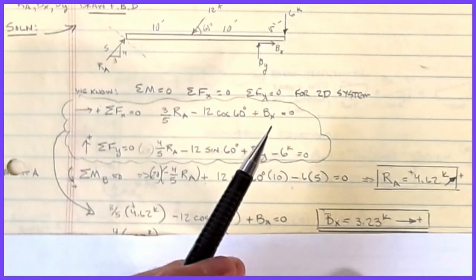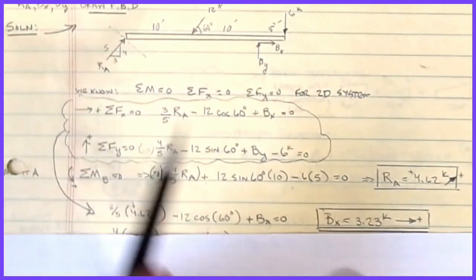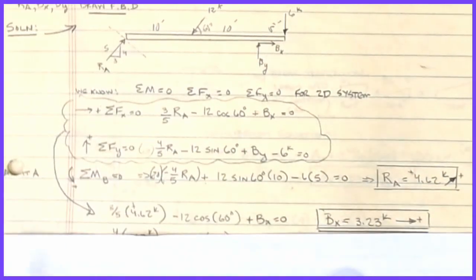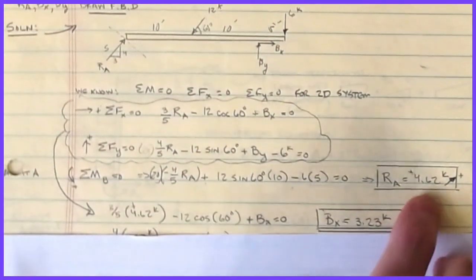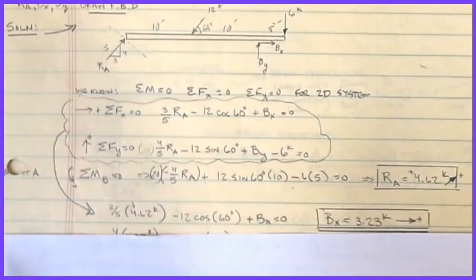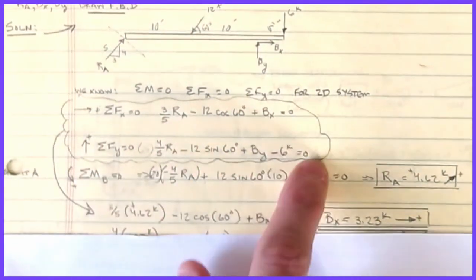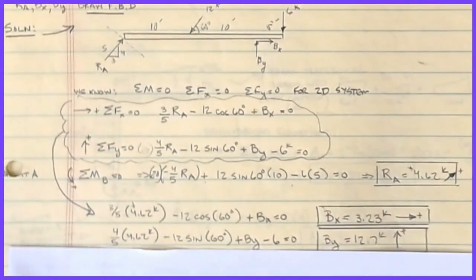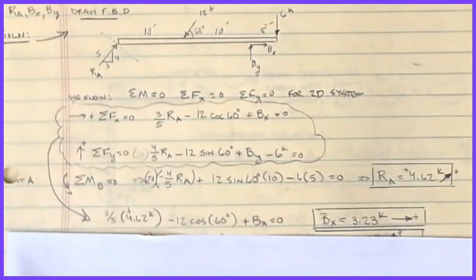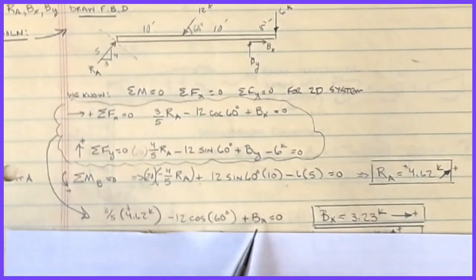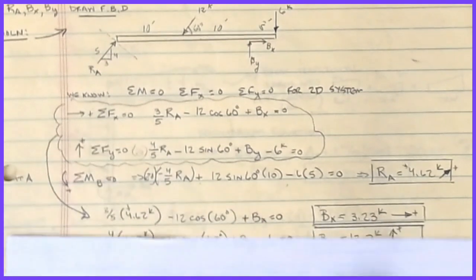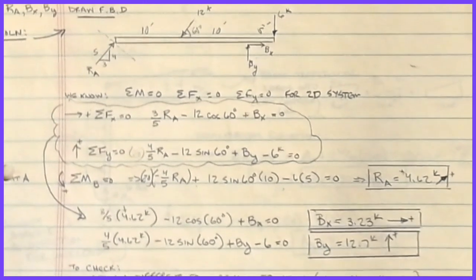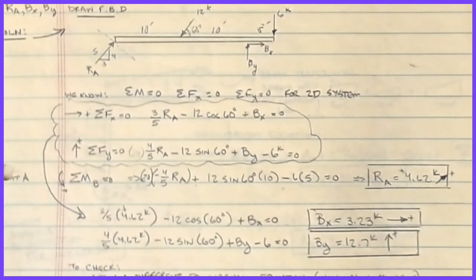So draw the free body diagram as you think it is, write the equations, and then don't ever change them. Just use the sign of the value to correct the equations for you. Because if I decide I did something backwards and fix the diagram, then I have to fix all the equations, and the more times I redo things, the more chance there is that you make a mistake somewhere along the way. Okay, so then we can come back in and do all these others. Just plugging in, I can find out that BX is positive to the right and that BY is positive upwards.